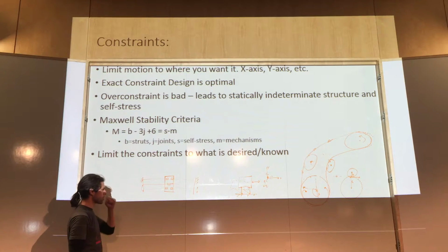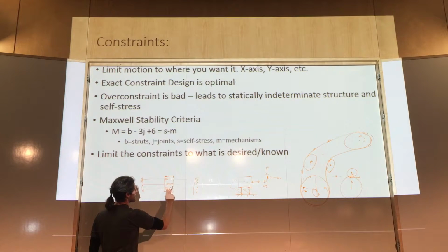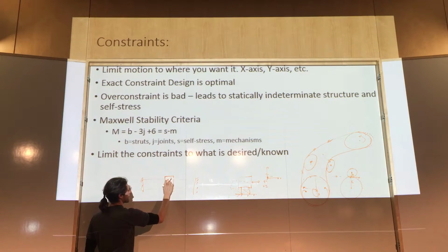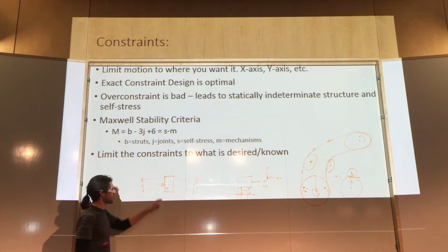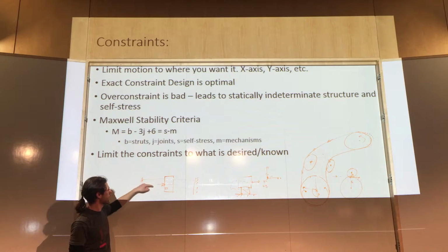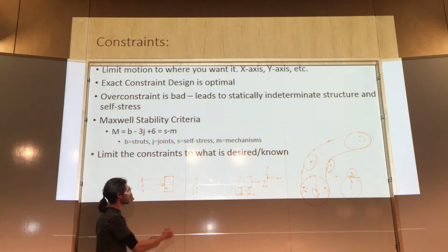Now, if you didn't have all these supports on it, say it was in a different configuration. They made it really nice and balanced, so it operates pretty smoothly. But what if you only had just one? You're like, okay, I'm just going to put this one bearing on it, and I'm going to put this shaft through here, and I'm going to apply a load in this direction. Well, if you only have one bearing here, you really only have one constraint that's keeping you. And so as you try to drive it, this thing's going to try to rotate and start to bind up on you.